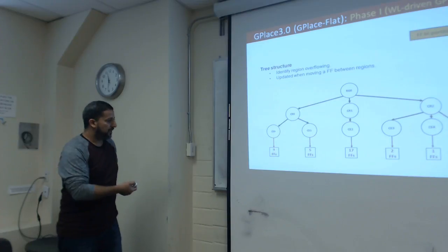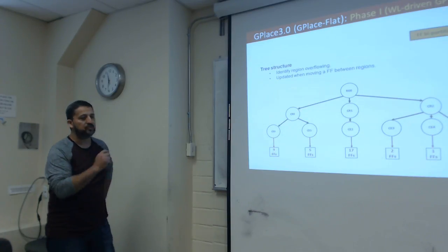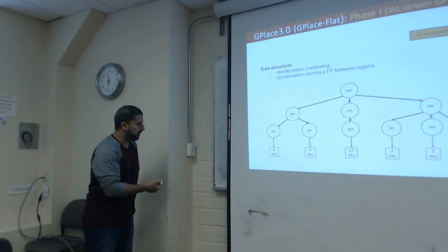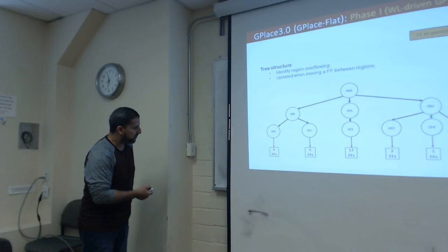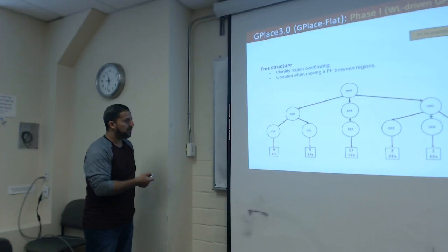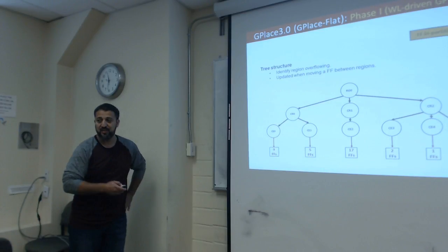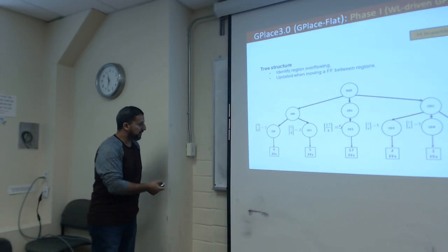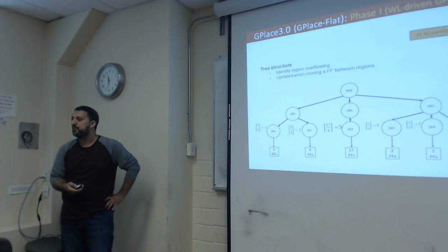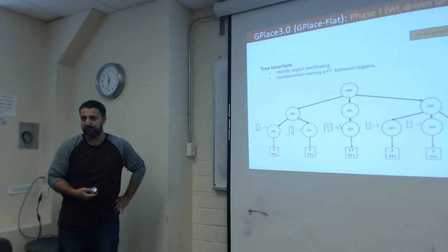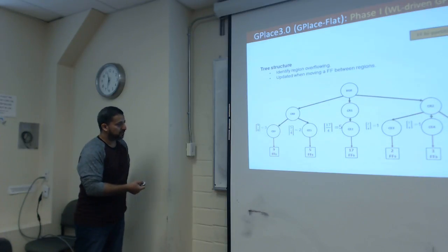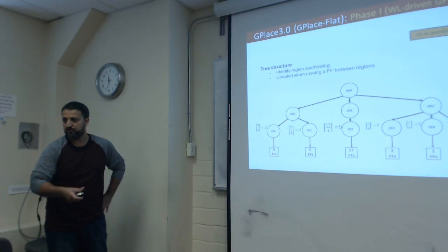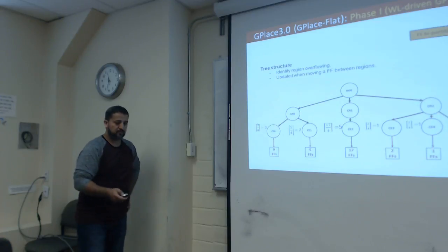So for example, if we have those 37 flip-flops in region 0, we need to identify if this region is overflowing or not. So here, by having this tree at the beginning, this means these 9 flip-flops share the same clock enable and have the same combination of clock and reset signals and so on. So we traverse the tree from bottom up to calculate the exact number of slices. By dividing the number of flip-flops by 4, we know how many subgroups we actually need for those flip-flops. Correct? Then we add those subgroups that share the same clock and reset signals, and divide them by 2 because each group has 2 subgroups. Okay. So we end up.